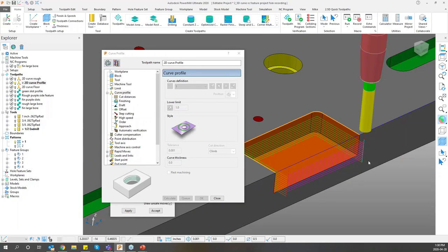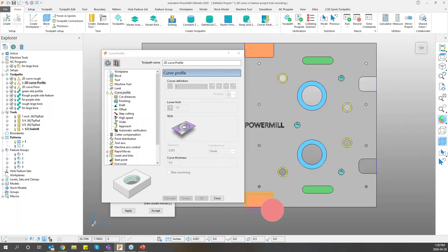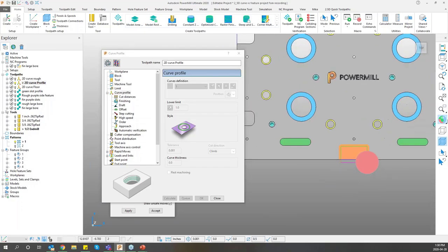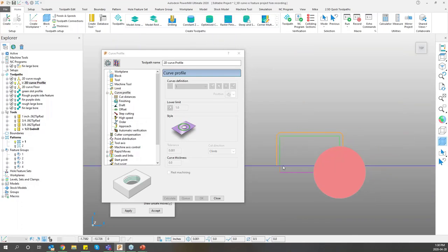The pattern, the way I always kind of explain that, is that it matters that it's from the top view. So if I go Control-5 from the top and undraw this, you can see the orange pattern here. That's the way PowerMill is seeing it. The min and max Z value height is driven with the information that you plug into it.